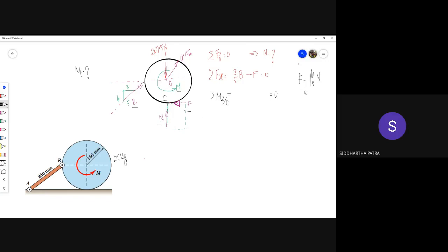So yes, that is our fourth equation. Okay, we will not be showing F equals mu s times n in the free body diagram, but we can write them in association with all the equations of equilibrium, and that way we can solve for all the unknowns.